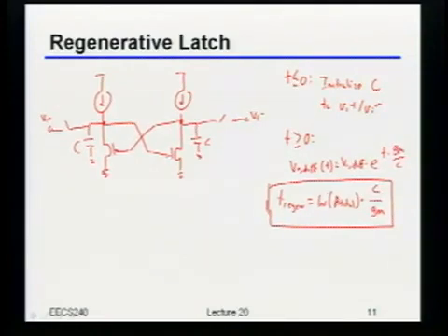So you'll see with a lot of these comparators, they're basically self-limited. The only reason you want to size these things larger than minimum is because maybe there are some other fixed parasitic caps in the system, and you want to make sure you're big enough to overcome those. There's actually one more reason, which has to do with offset, but we'll talk about that later. With a lot of these comparators, you have a very strong motivation to make these devices as small as you can.